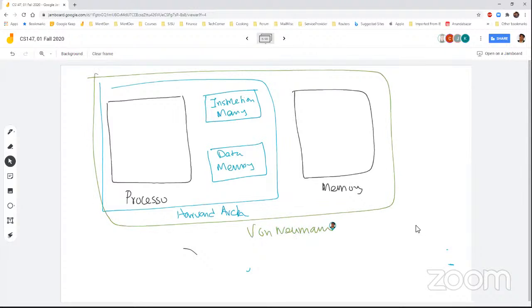Okay, and your data flow to and fro from the main memory, this is now what we call the main memory, to the instruction memory and data memory, and the processor individually interacts with them. So from the processor viewpoint, there is no single memory called main memory. Now it is divided into two separate memories, instruction memory and data memory.